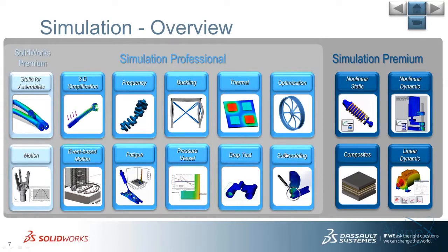If we go beyond that yield value within our load case, the material will permanently deform. The forces get so high that the material won't deform back to its original shape. That's usually the first point of failure that a lot of companies design to.